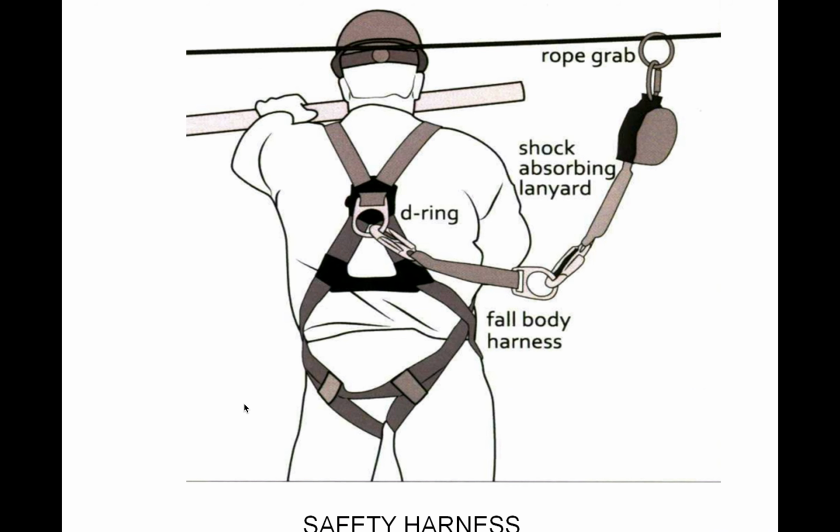All right, we saw the front of a safety harness. This is the back. So basically you have a ring there in the center, centered over the back, which is ergonomically the best point to have that in case you fall, so it doesn't break your pelvis or strangle you around the neck, if you do happen to fall. And then you have that connected to the harness.